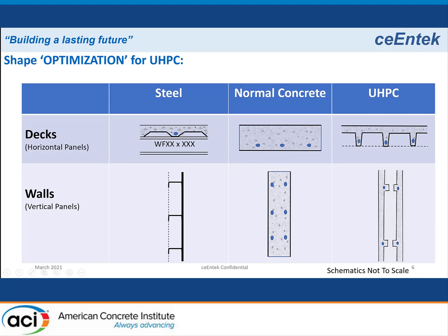And when we go to wall panels, what I've shown here is an insulated wall panel. So you can have a layer of insulation in between 2 wythes of material, again with ribs to stiffen for deflection. And if you put this panel into load bearing, you want to make sure that you don't get too much buckling and bowing, because then you get eccentricities which amplify the bending moment in the panel. So you end up with this type of shape profile to stiffen the thin panel skins on a wall panel. So that's the type of optimizations that these kind of mechanical properties tend to drive.